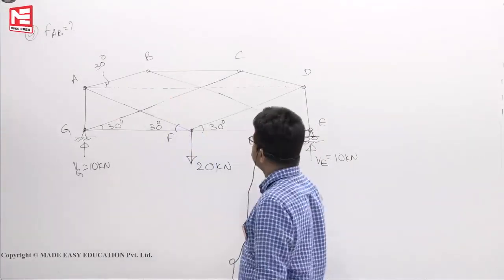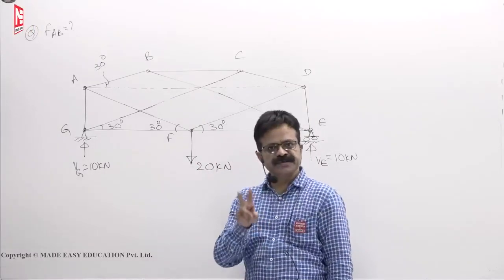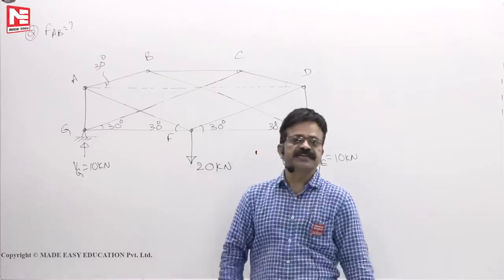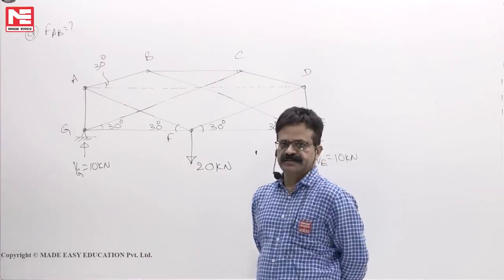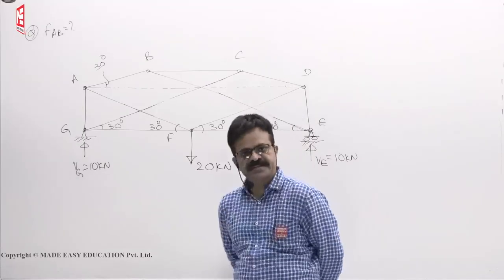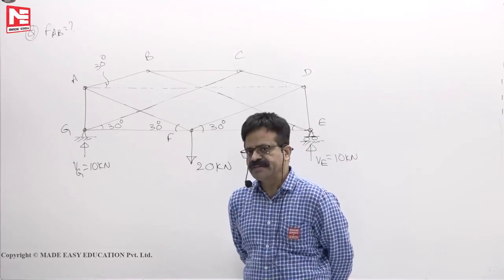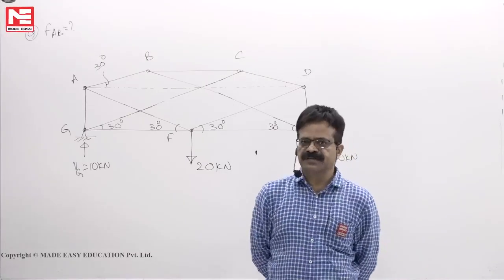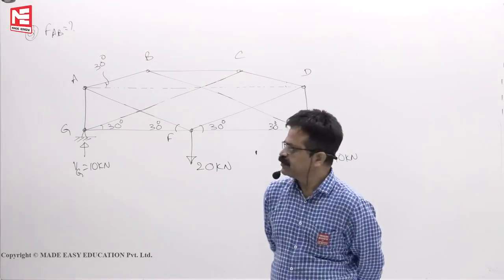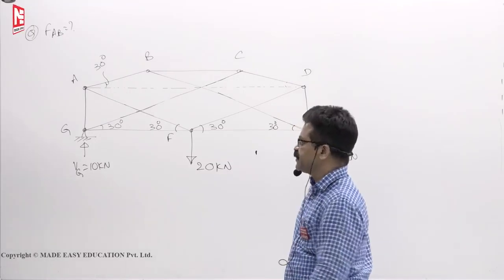Out of this entire truss, which joint has only two members, so that method of joints we can use and break it. See, you will find that in this truss, all the joints have a minimum of 3 members. So, method of joints directly we cannot take, sigma x 0, sigma y 0, without understanding, we cannot make that. Next, method of sections.